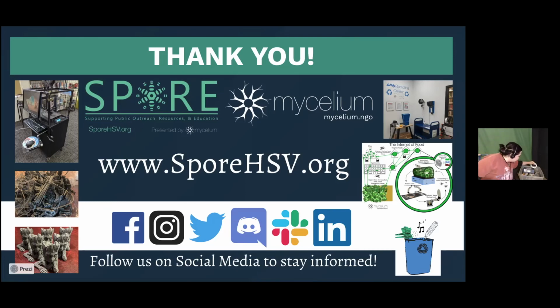So you have to be really careful with letting it get moisture, especially since we live in the South, so it gets quite humid here. Now, if your filament does get any kind of moisture, you can try to put it in the oven. Or I think I saw someone say something about using a dehydrator. I believe you can do that. I've heard of people doing that.